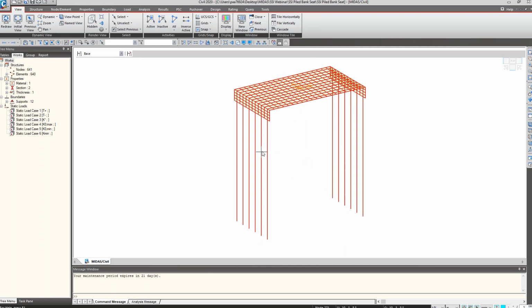The way that we decided to model this bridge is basically shell elements for the deck, because we are assuming that the deck is going to be a concrete solid slab, shell elements for the abutments as well, 1 meter thick, and then for the piles we have beam elements representing that. So the first mission for us with this model is that we want to understand what is the movement that we can expect.